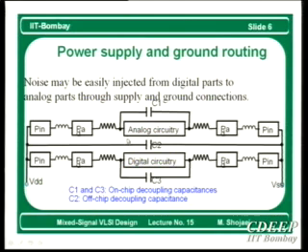Now, anyway, if you notice, we use 2 different pins to separate digital and analog supply right from the pin side. The reason is because the VDD line and ground line or VSS line in analog is usually not very noisy. It's quiet. It's clean. But in digital, it is fully noisy. Therefore, we want to separate them right from the beginning. Okay, so this is one of the reasons we have this connection. Therefore, we have the entire analog modules on one side, digital modules on one side, and this side is again the VSS connection in the same fashion.